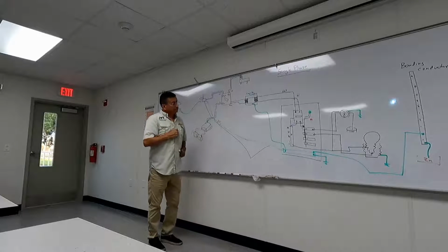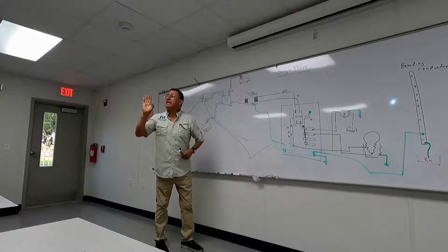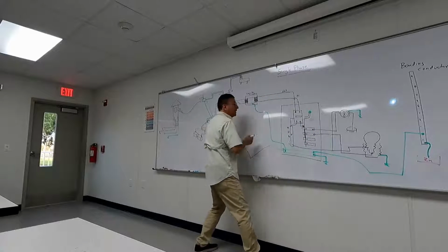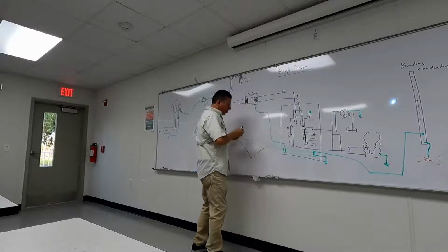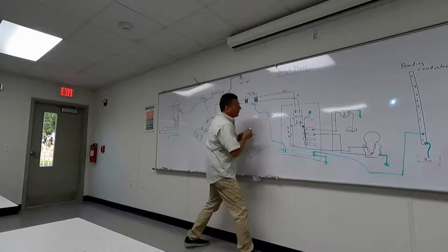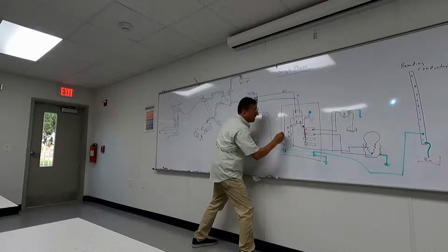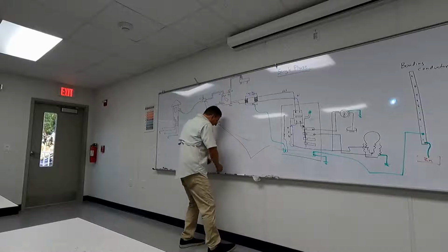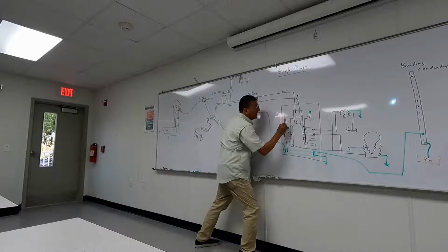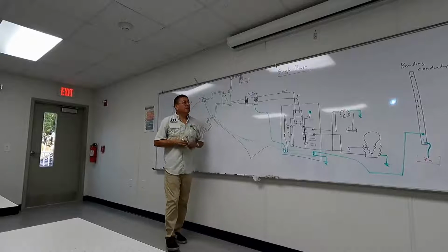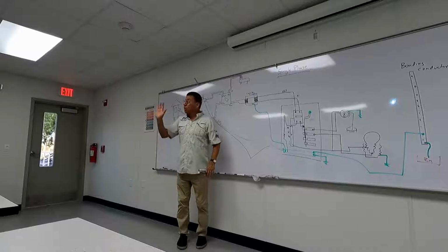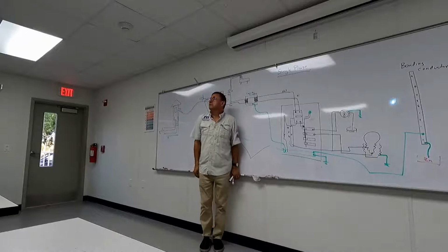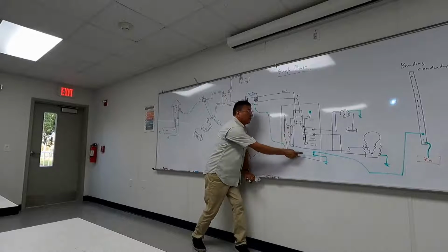Look at this. You have another LED, the red one, normally connected with one leg with a resistor to the ground bus bar, and the other leg connected to the neutral. If the connection is originally good, this is hot and this is neutral, this light is off, because you don't have power here and you don't have power here.